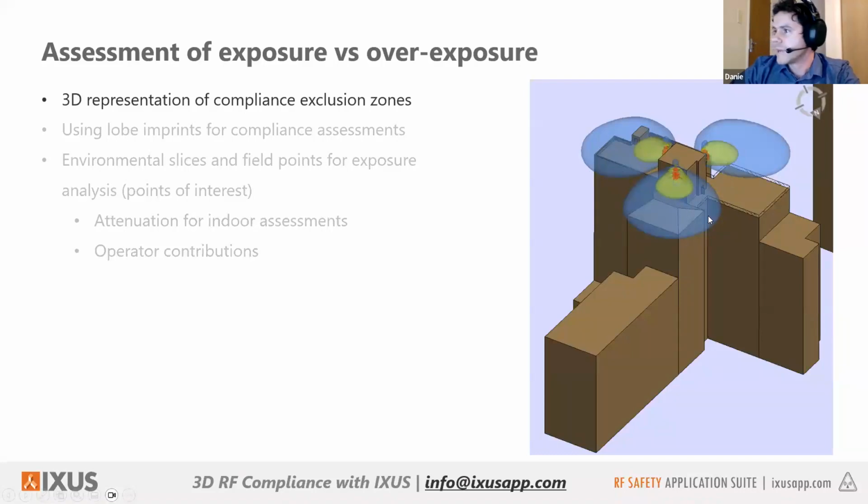And already we can now see that a lot of these other surfaces that we have created, like for example, this structure over here and over there and over there, is actually quite far away from our overexposure areas. So just by looking at this picture, we can already see that we do not need to apply a lot of detail to these structures here at the bottom.